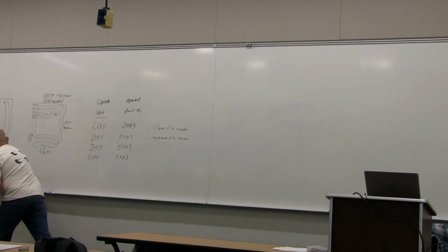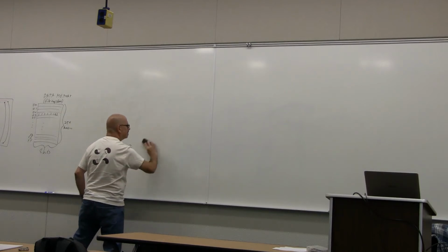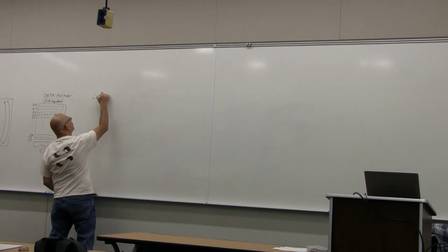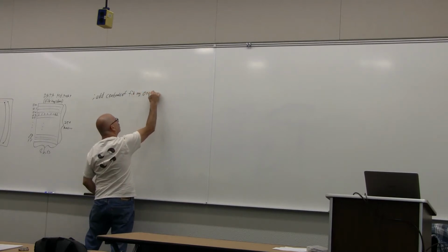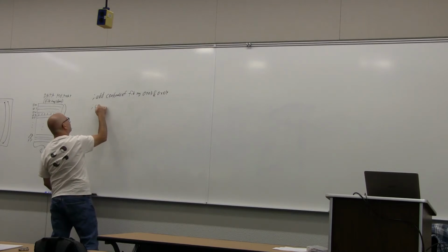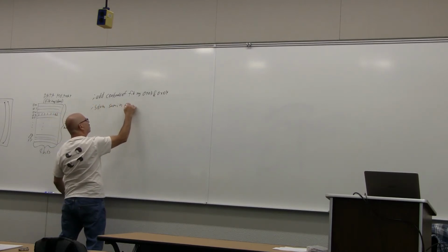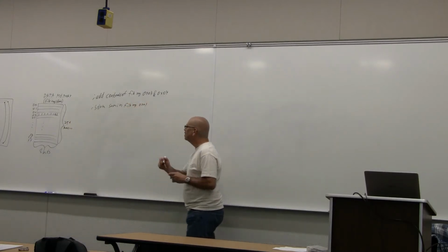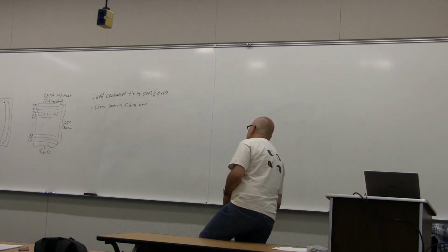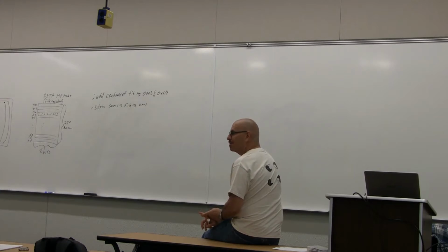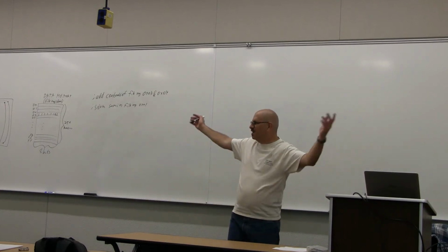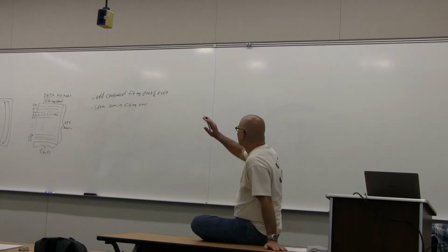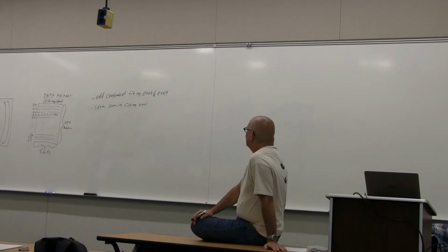So let's write a comment. I want to read 2 file registers, add their values together, and store the sum in 0x01. And I'm not trying to add 3 and 4, okay? I'm trying to add what's stored in file register 3 and file register 4. Add those values and store in file register 1. And the short answer is we can't do it. At least not with one instruction. There's no instruction to do this. Why? Because this chip costs $1.